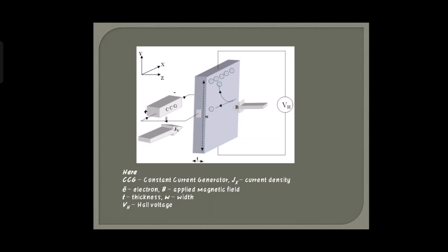Suppose we place a magnetic field in such a way that it is perpendicular to the direction of the current, it produces some distortion in the charge. Then a Lorentz force is induced and it makes the electrons drift towards one end of the conductor. The other end has a depletion region, which has a deficiency of electrons.